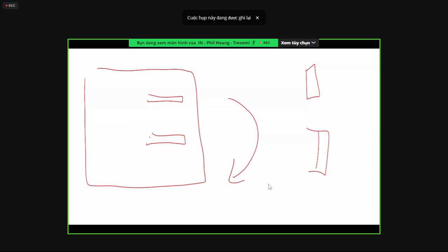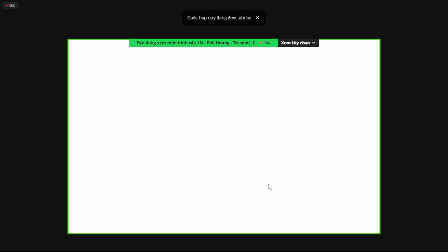That's what it means. I hope that answers your question. Can you explain why introducing clock skews is the reason the designer prefers to place high performance, high power consumption macros away from each other? That is not the correct answer. It's not introducing clock skew. I don't know what makes you think that is the right answer, but the right answer for placing high performance, high power consumption macros away from each other is for the reason of the voltage drop, right?